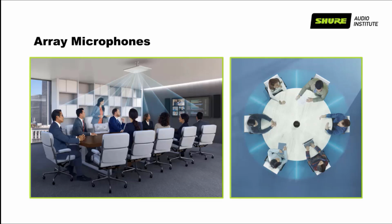Right. So the directionality, the distance factor, the physical design, all of that could apply to a dynamic or a condenser microphone. And there are some pros and cons to each. A lot of what we end up talking about here, particularly in these AV conferencing applications, are condenser microphones, because they're more sensitive, which is needed since the microphone ends up being further away from the sound source. And condenser microphones can be made much smaller as well. So if you look at the ear-worn or lavalier mics or even the little gooseneck mics, they're very tiny, and that's something you can only really achieve, and still have it sound good, with a condenser microphone. But the concepts here could apply to dynamic or condenser.